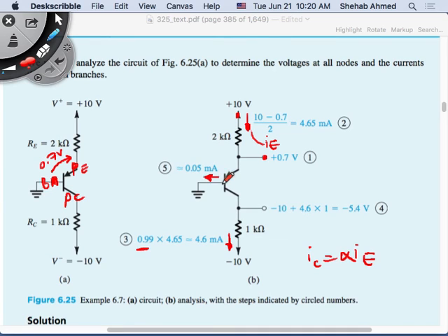Note that IB isn't coming out of the device. Like if you look at the equivalent, yes, always coming out of the device. All the polarities of all the currents have changed. Because remember, initially in the NPN, the current was entering the collector, and it was exiting the emitter. Now I flipped, because I flipped the device. The emitter is entering. Here the emitter entering current, the collector exiting current. But base current is also flipped. But the process is exactly the same.